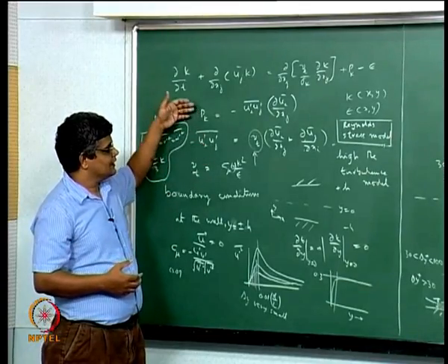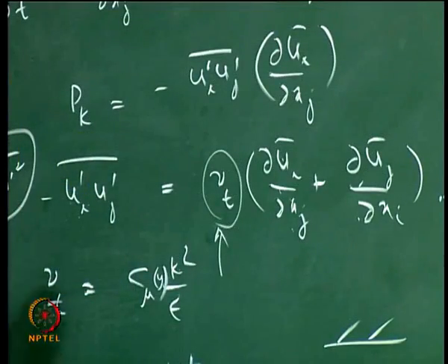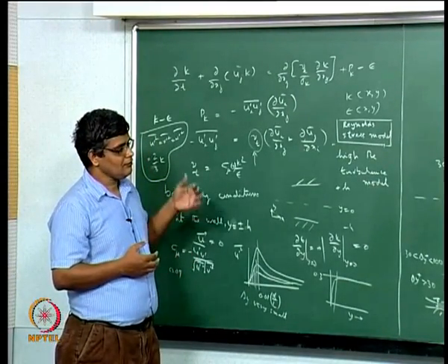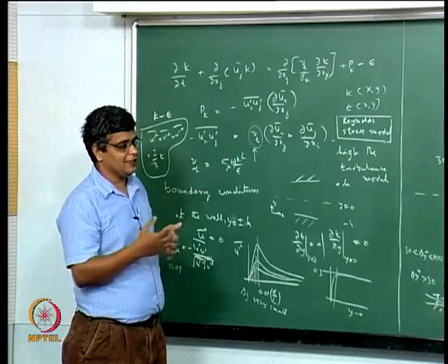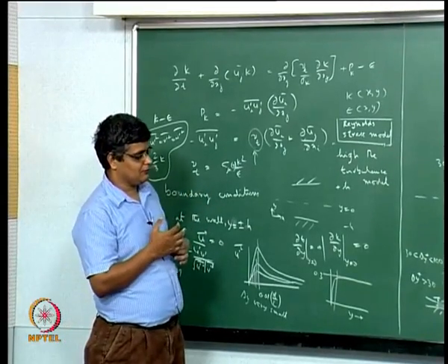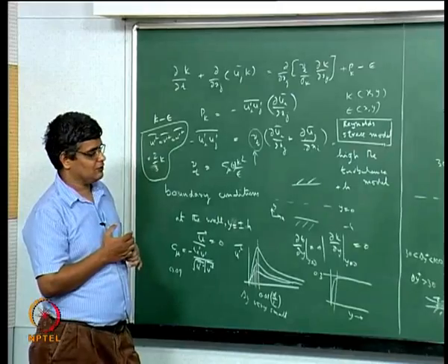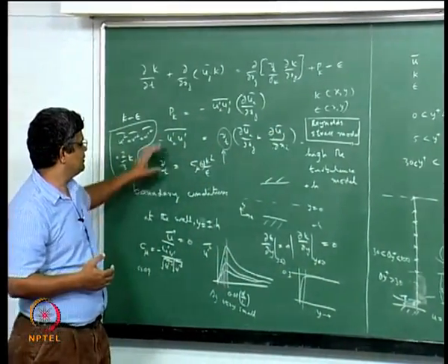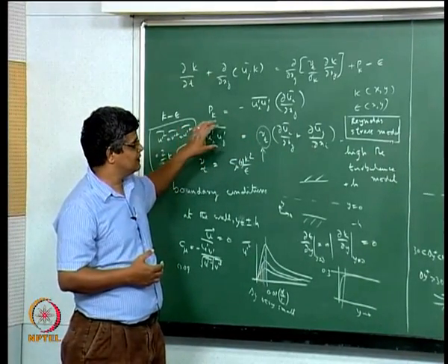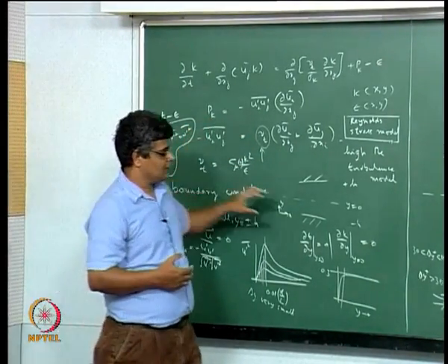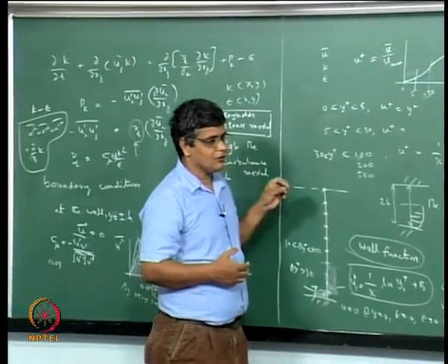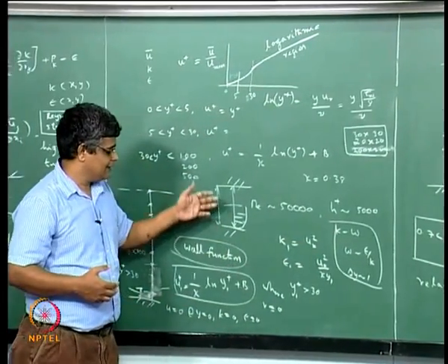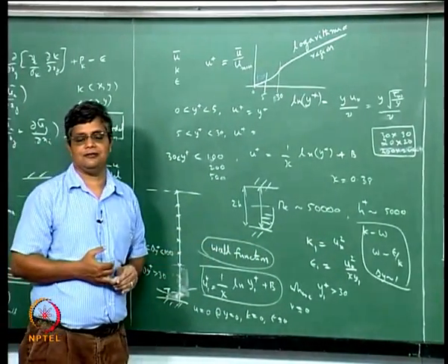Although the standard K-epsilon model has proved to be a robust model, it may not always give the correct values, and if so we have to anticipate what kind of flow phenomena we are looking at, and choose to either go for a Reynolds stress model in case strong curvature effects or strong buoyancy effects play a part, or if we are looking at strong wall influence, we may have to go for these types of models, or we may have to take a careful look at the wall functions that we are using.